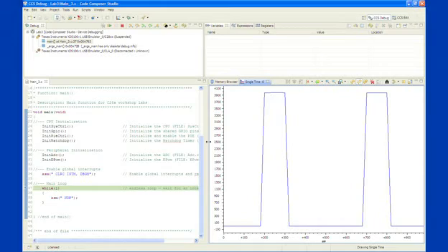What we'll do is we'll measure this waveform. So we've generated a 2 kilohertz 25% duty cycle symmetrical PWM waveform. The period of 2 kilohertz is 500 microseconds. So let's confirm this with the measurement marker mode.